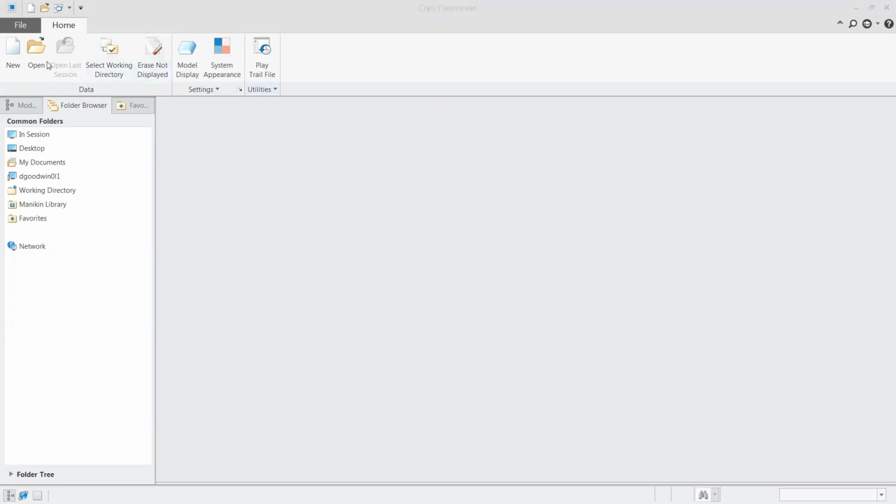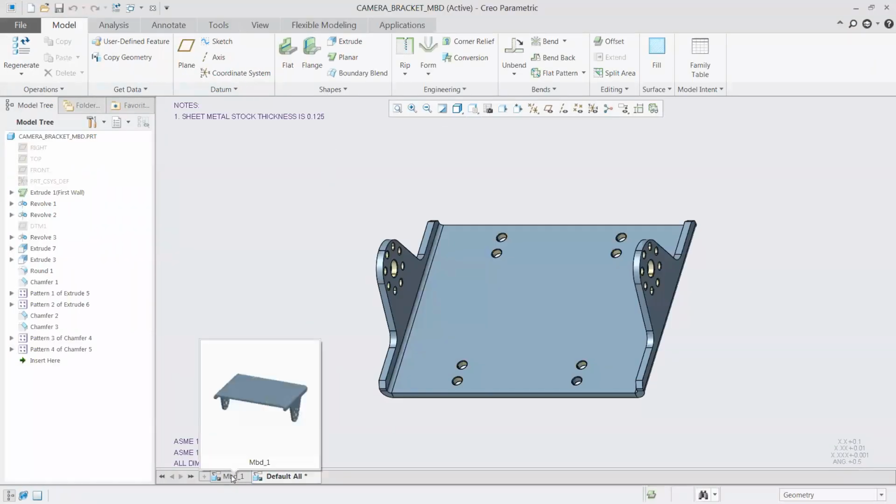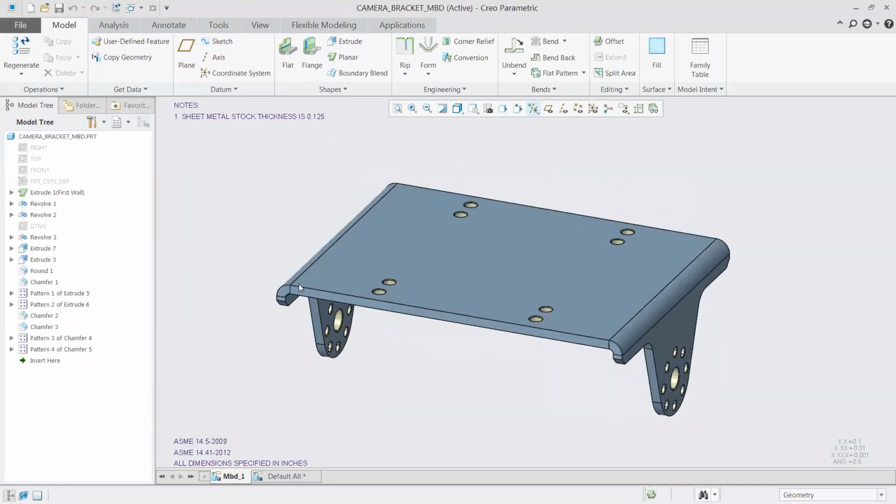Cool. Going back to John's question regarding the 4x callout, by the way, he was saying the definition of the 4x callout didn't reference the 4 holes, though. Yeah, so what we did for the 4x was simply just a prefix, right? So that part specifically isn't referencing the 4 holes. It's up to how you want to define it, right? I can go through and show how that works on one of these models here as well. You could either have it reference all 4 of the surfaces, or in that case, they may have just wanted to reference one surface and then, from a prefix or additional text standpoint, use that in the callout.